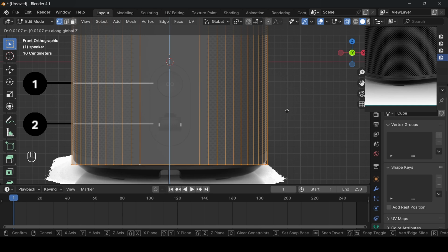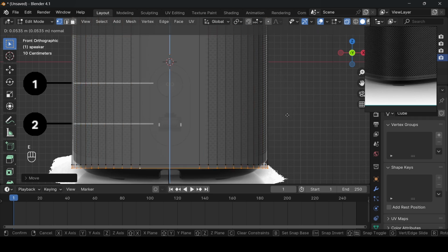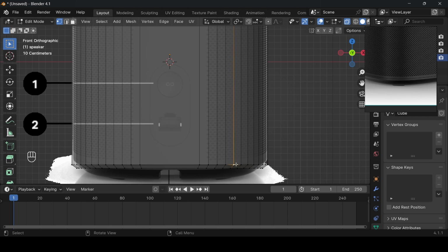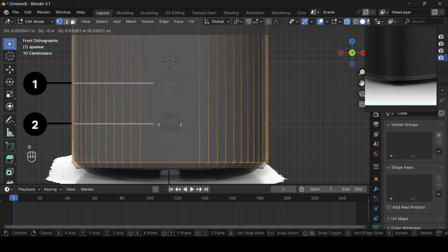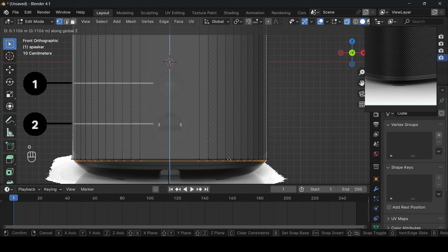It's quite hard seeing from this. It's not front on in front view or back view, so to say. So I'm just going to press E to extrude this, and I'm just going to scale it down like so, maybe something like this. Then I think I'll still bring this up a bit, still about that corner. So I'm going to select this ring of vertices here, press G Z, and I'm just going to move it up to this point. Just have to play around to have something matching. Then I'll press G Z to bring this one right here. Just bring it here.